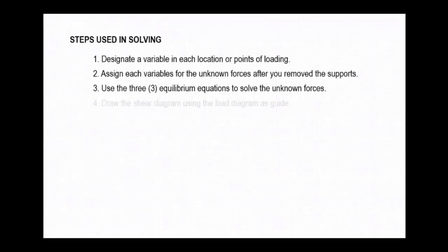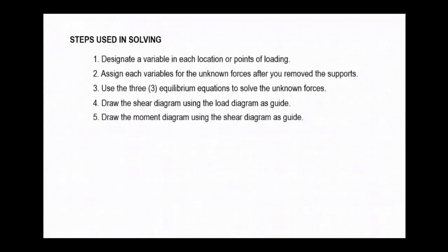Next is to draw the shear diagram using the load diagram as a guide. In drawing the shear diagram, we will consider the support reactions and the external forces. And lastly, draw the moment diagram using the shear diagram as a guide. In the moment diagram, we will consider all the areas generated by the shear diagram.